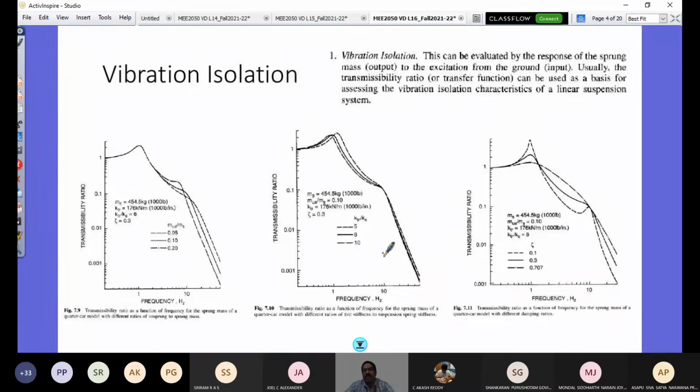It's a parametric study. So you have three parameters. What are those? One is the mass. Another one is the stiffness. Another one is damping. So when I say mass, stiffness, damping, masses are two, sprung mass and unsprung mass. Stiffnesses are two, Ks and KTR, and dampings also are two. I consider only shock absorber damping. Why? Because comparing the damping value of your tire to that of shock absorber damping value, that's insignificant, we have seen. So in your model, you have these parameters, right?